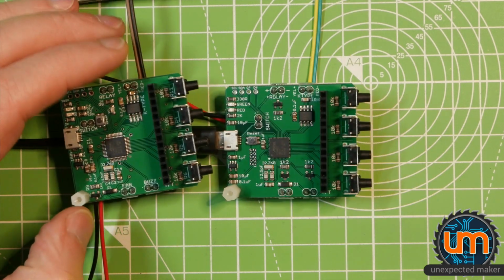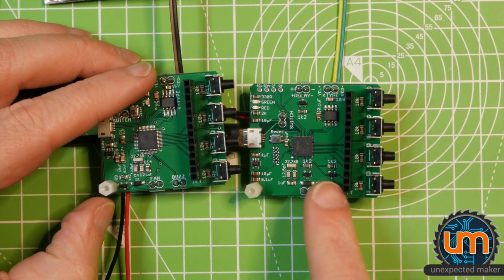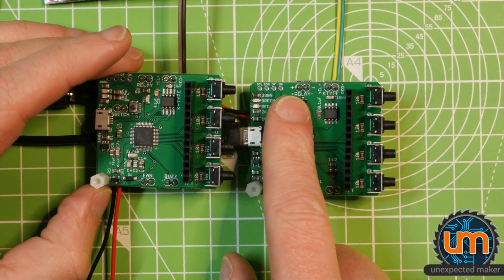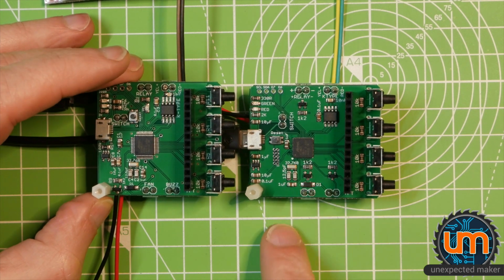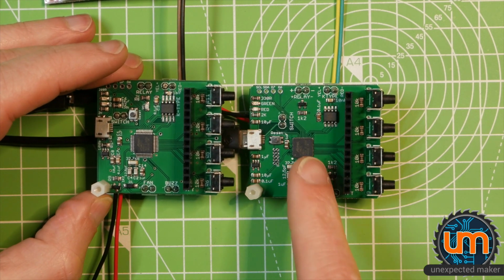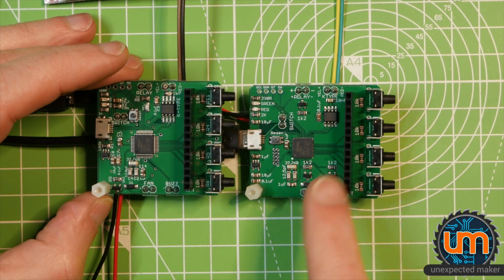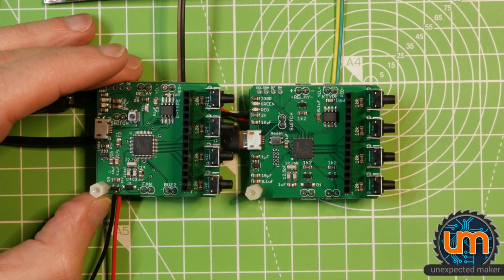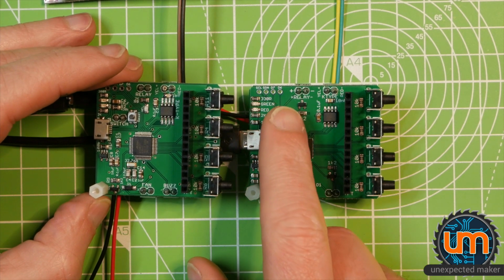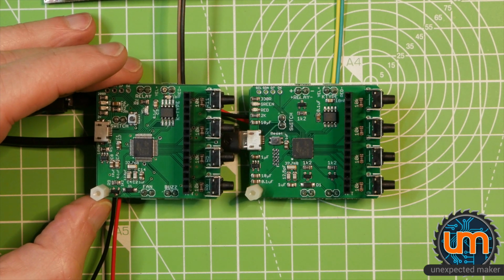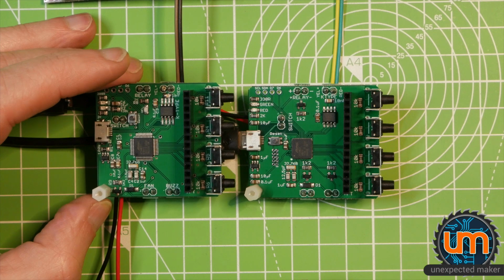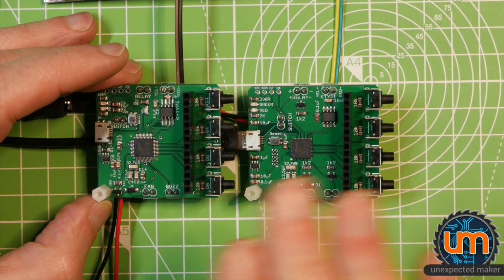And what I also did was added some transistors to the relay and to the buzzer to be able to fire them off 5 volts instead of using the 3.3 volts from the GPIO. That way I get a louder buzzer sound, and I can also allow people to control SSRs from 5 volts and up, because it turns out that some SSRs can't be controlled at 3.3 volts, like mine can. And everything's been working fine.